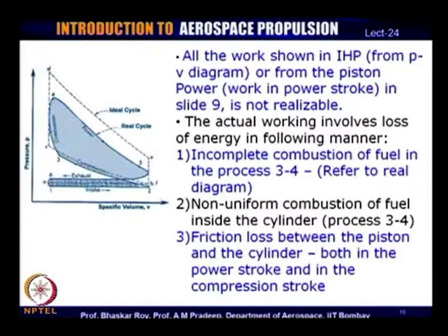Then we look at the fact that the piston is moving. Now, the movement of the piston of course entails, as I said, the mechanical friction loss between the piston and the cylinder body, and it happens twice, once during the power stroke and once during the compression stroke. So, the friction losses would have to be brought into the reckoning while considering the real efficiency of the engine.